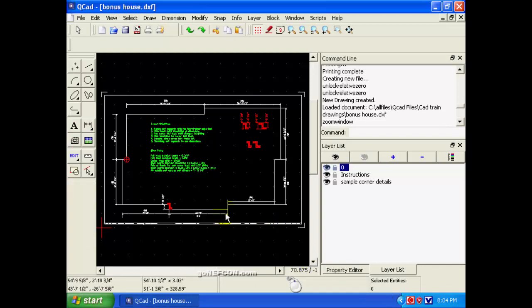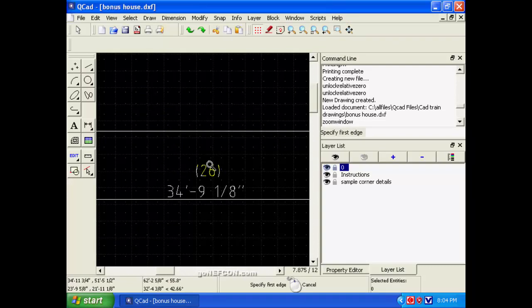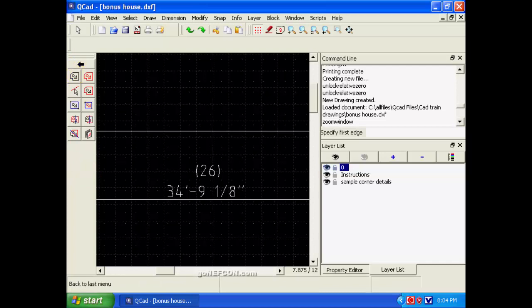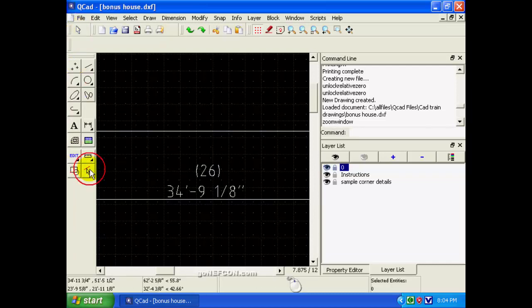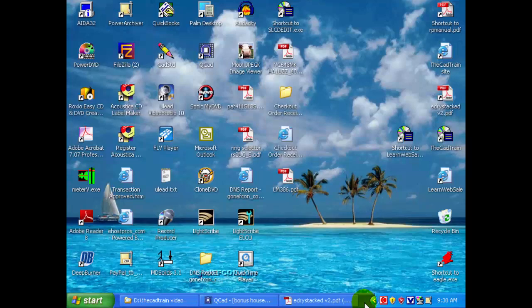This is another example of always being vigilant. When we move this wall over 7.625 inches, this dimension now no longer fits the number of blocks we have listed above it. It was 26 blocks, now it's not. That number does not equate to 26 blocks. So what I suggest you do is delete the 26 blocks text for right now. Because it's a lie.